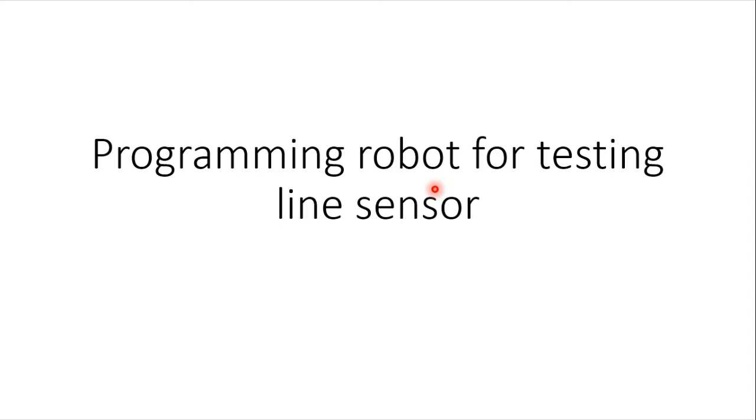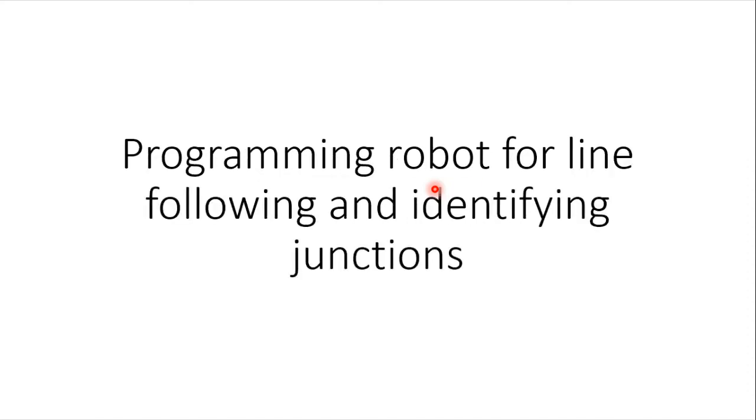And as a conclusion for that particular section of the tutorial, we have seen that whenever you have a line sensor which is arranged in a specific geometric pattern, it becomes a little bit easy for us to identify the junctions whenever we are coding. Alternatively, we can go for some discrete sensors where you are able to place the individual sensors as and where you need on the robot. So the placement is going to be a little bit flexible. I'm going to show you this in a couple of minutes from now.